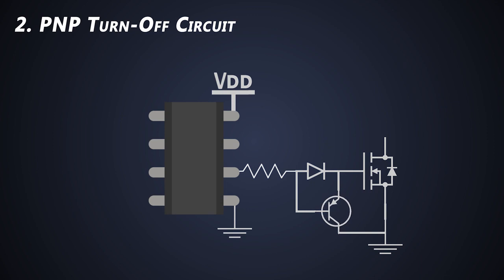The most important advantage of this solution is that the higher peak discharge current of the MOSFET input capacitance is confined in the smallest possible loop between the gate source and collector emitter connection of the two transistors. Also, the turn-off current does not go back to the driver. It does not cause ground bounce problems, and power dissipation of the driver is reduced substantially. The turn-off transistor shunts out the gate drive loop inductance and output impedance of the driver. Furthermore, this BJT never saturates, which is important to be able to turn it on and off quickly.